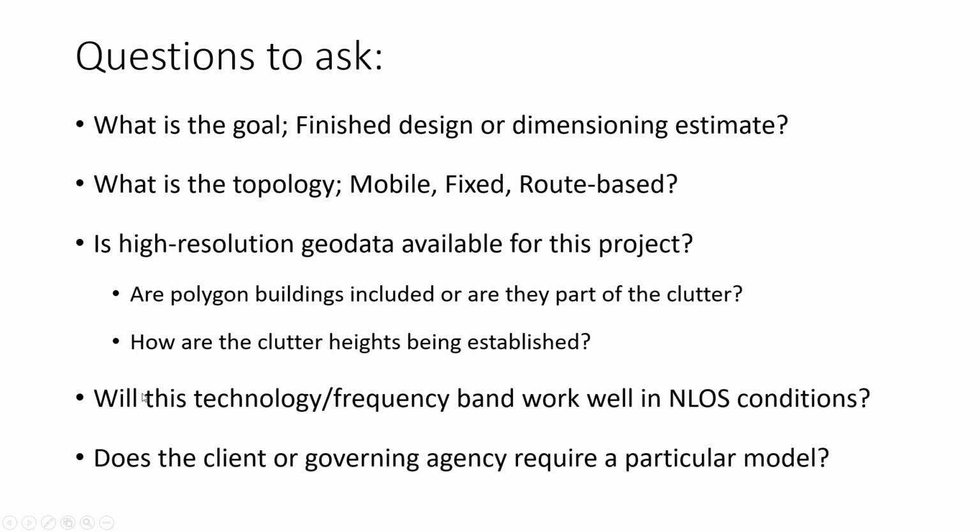Is this technology or this frequency band particularly sensitive to line of sight conditions, or is this a technology that's designed to operate in non-line of sight? Very often my modeling choices will vary based on whether I'm trying to guarantee line of sight or very near line of sight to all of my links. And obviously, finally, does the client or the governing agency involved require a specific propagation model? And if so, I need to understand those requirements.